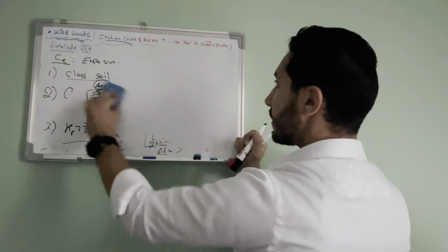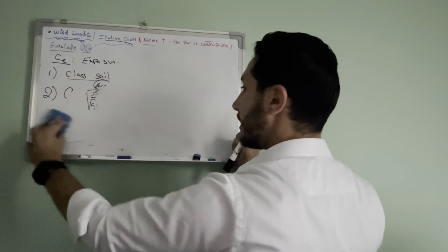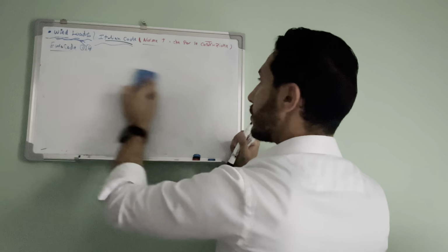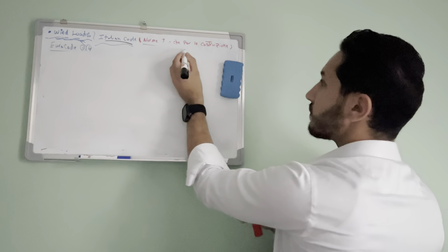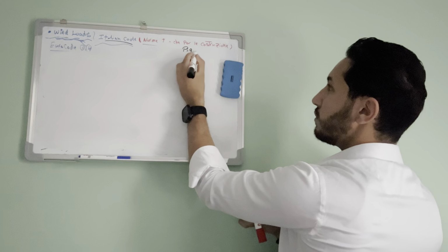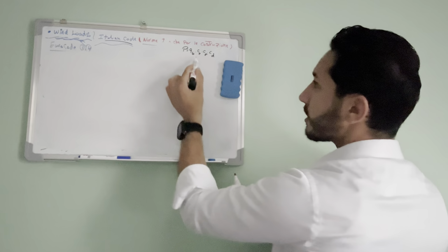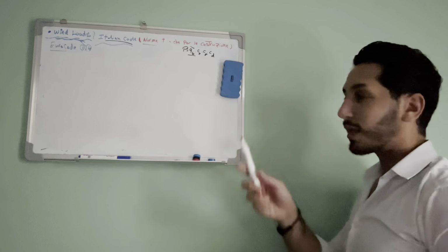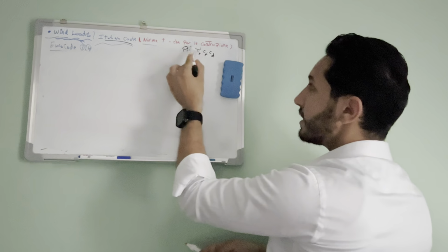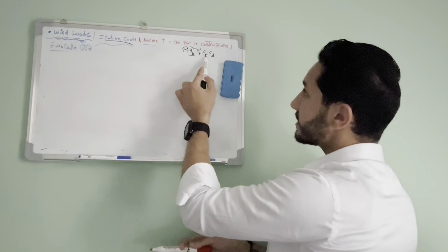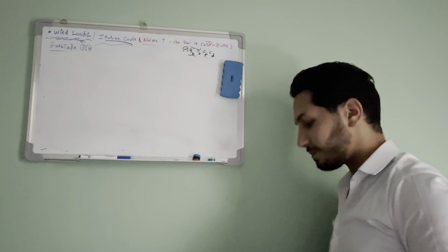Now we calculated, okay, I will just write in here the equation real quick. So we have the pressure equal to QB times the three coefficients, right? CE, CB, CD. The QB is already calculated, or we defined it. CE, we just got it. Let's go for the third coefficient, which is the shape coefficient.